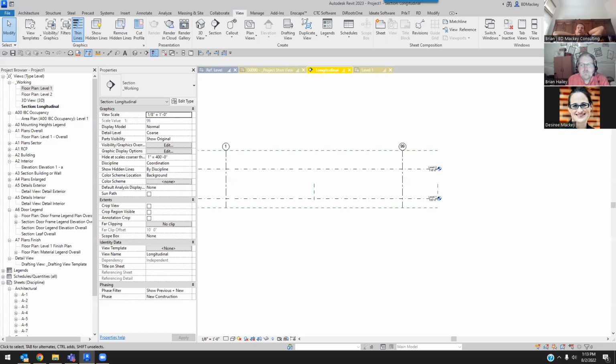So there's a considerable amount of work to get that family and create that family, but it is something that I have had structural engineers do. That way they can tag the door opening when they go through and set this up. But again, they're using copy monitor to get them in originally from the architect's file. That also means you have to have a wall there to host it into. I've seen somebody, and I can't remember if copy monitor worked, where they just created a non-hosted door family, and I think they could still copy monitor the architect's doors for theirs. But I'm not exactly sure, I think you were able to use copy monitor, but I can't remember for sure.